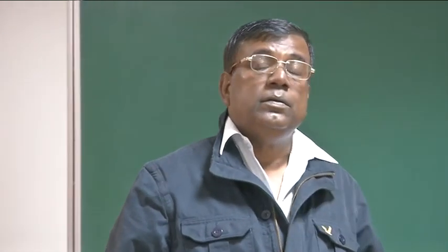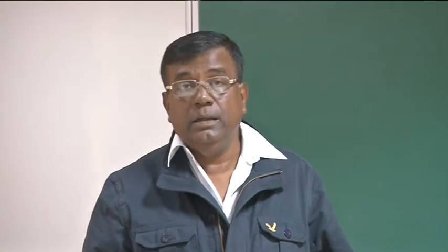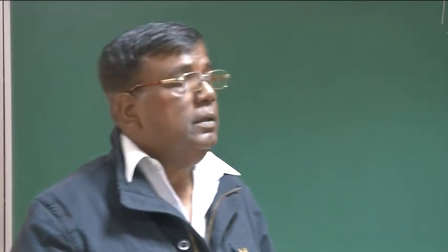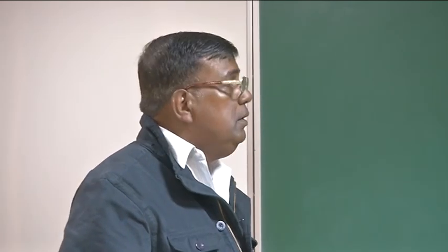And as I promised, we'll have a session where we'll focus more on how to implement whatever we have derived: understanding delta E required, how to calculate Cm naught, how to design an airplane to have a particular Cm naught, and what the elevator deflection required to trim an aircraft should be while it is climbing, cruising, or landing. We also know what happens when the aircraft lands very close to the ground. With this background, we will try to solve one or two examples, maybe one example in detail today.